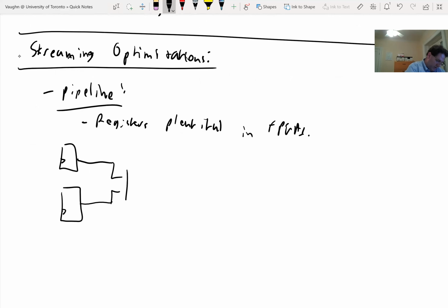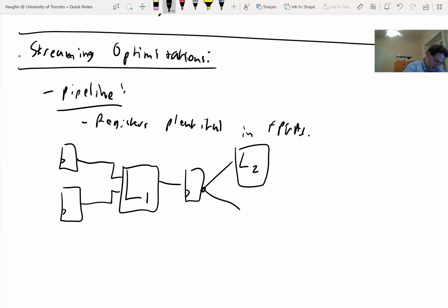Okay, so we've got registers, and I'm showing you something fairly fine-grained. So let's say registers and lookup tables. I'm looking at a register, a lookup table, and then that goes out to another lookup table. This register fans out to two different lookup tables. I'm just labeling them all with a number, so L3 and L4 and L5 all have different functions.